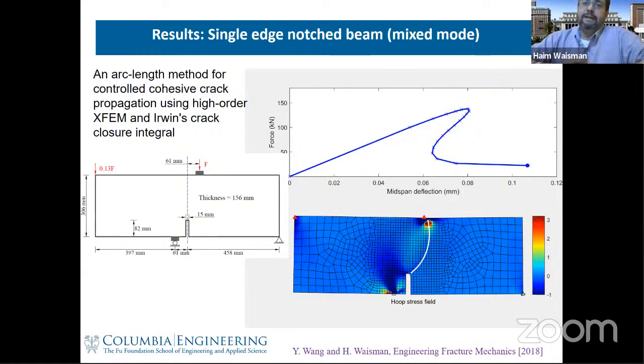And so an anisotropic degradation function would make sure that only the diffusion normal to the crack will be degraded, but the one that is tangential to the crack would remain untouched. So this is something that we have worked on, and we show that indeed, if we want to recover a better discrete formulation, we need to use an anisotropic degradation function.